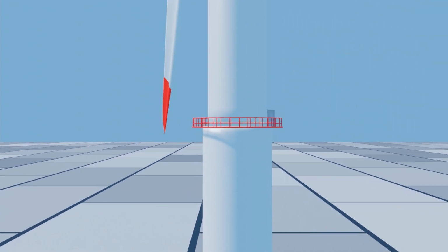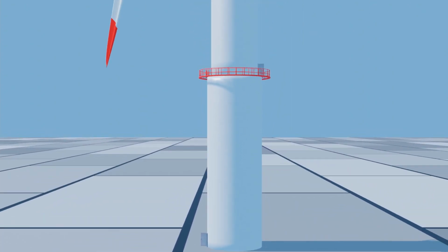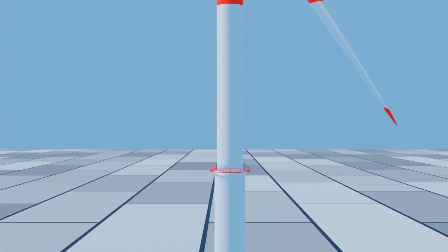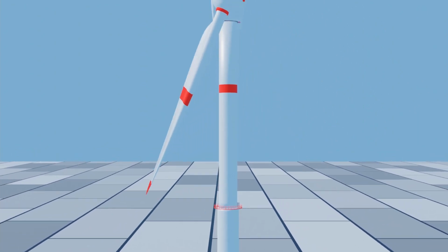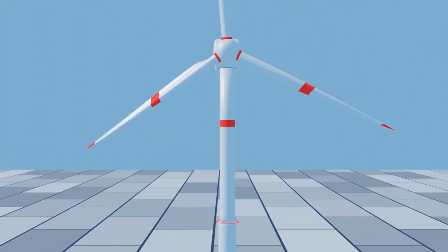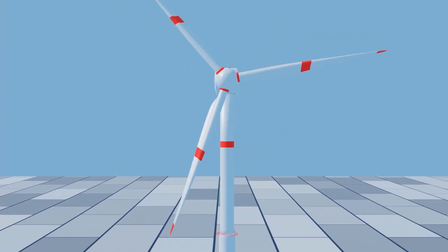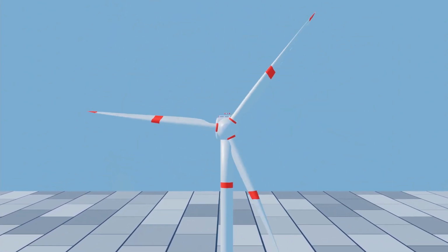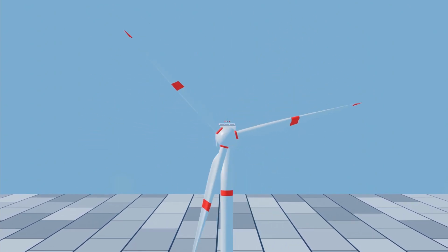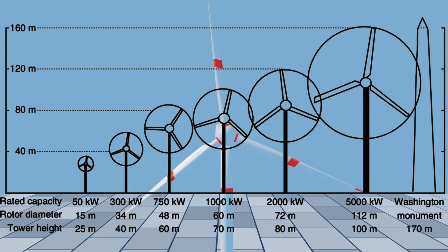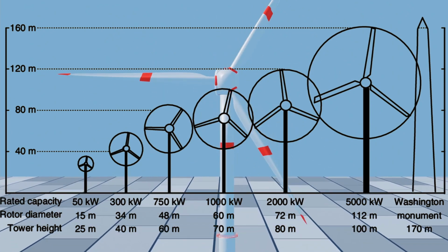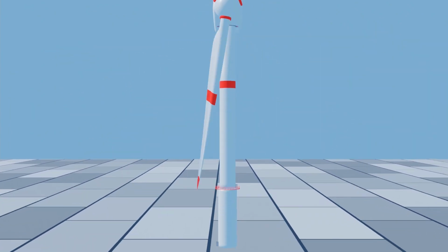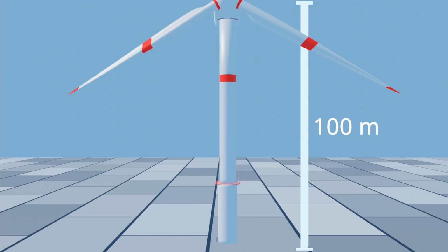The tower is a crucial part of the wind turbine that supports all the other parts. It not only supports the wind turbine but raises the turbine to a sufficient height so that the tips of the blades would be at a safe height during the rotation. Not only that, we have to maintain the height of the tower so that it can get sufficiently strong wind. The height of the tower ultimately depends on the power capacity of the wind turbine. The towers of wind turbines in commercial wind power plants usually range from 40 meters to 100 meters.